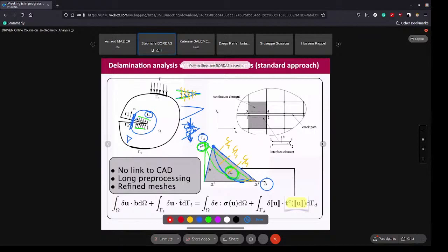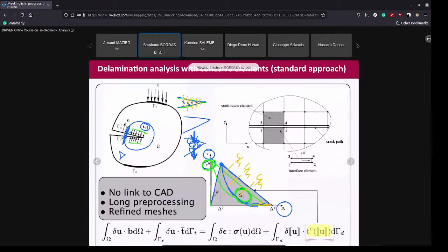If you do that, then you see that there is also a nice advantage, because if you have a traction-free crack here, sigma goes to infinity. So the stresses go to infinity when R goes to 0, meaning when the distance to the crack tip goes to 0. When you have a cohesive crack, the idea is that you regularize this infinite behavior at the crack tip by closing the crack faces using some sort of traction-separation law, which allows the crack, instead of closing in an abrupt way, to close smoothly, like for example this way.